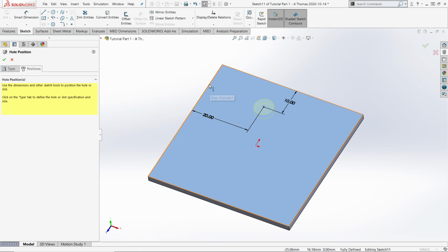But if I do it from the edge, it's nice and easy because he can just square up the plate in the equipment for marking it, and he can mark where 20 millimeters is, and he can mark where 10 millimeters is, and he can line up the drill press or the mill with that point that marks that.